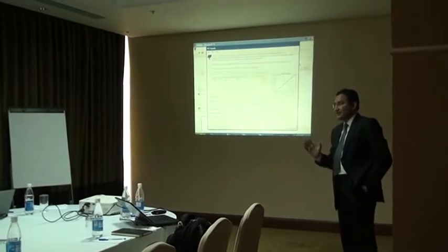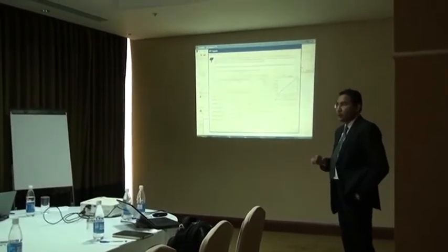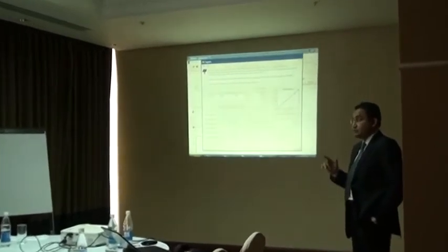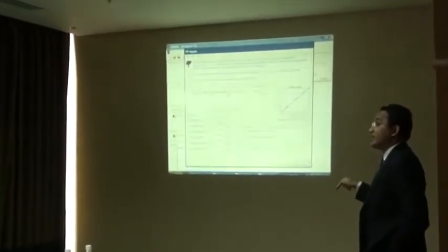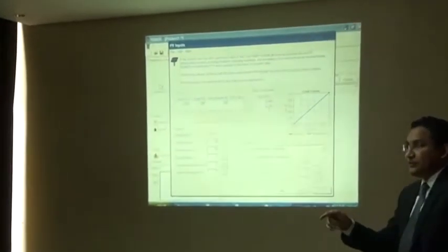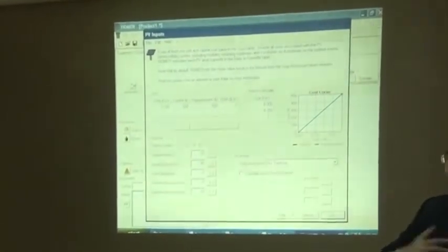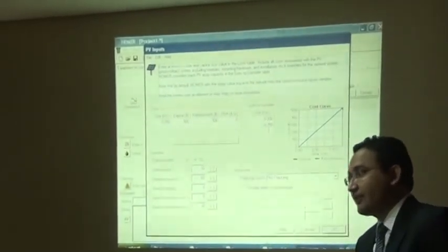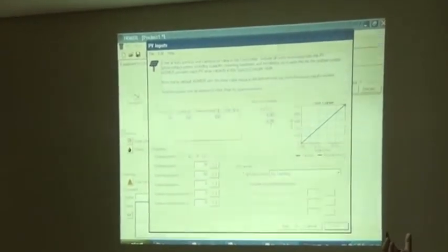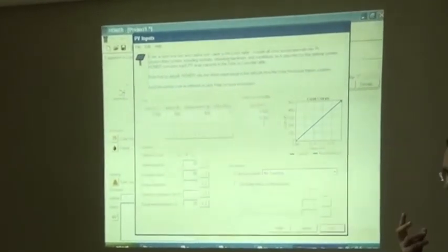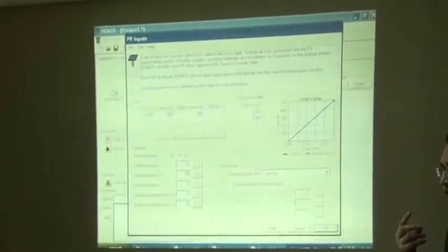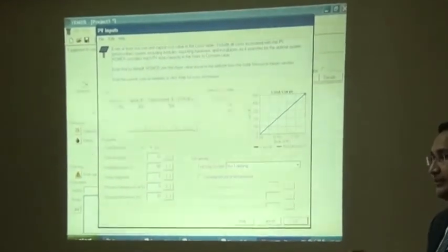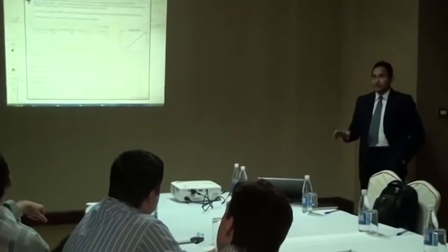And you have a space limitation where you know that you can go up to 16 PV modules. That means 4 kilowatt. So you can go up to 4 kilowatt of sizes to consider. But if you think that you can go up to a larger footprint, you can go further. You can go up to 10 kilowatt, 12 kilowatt. But always bear in mind that there are two things. One is the design is done before you go for the procurement and before you go for the real implementation.